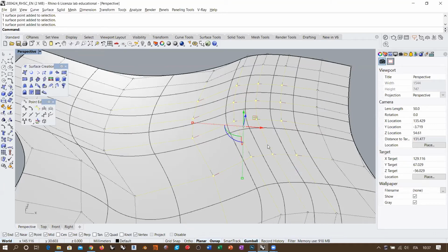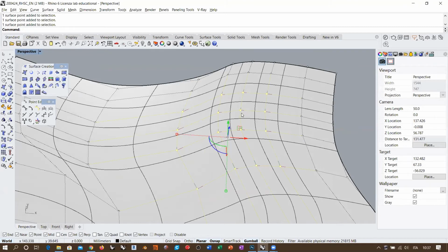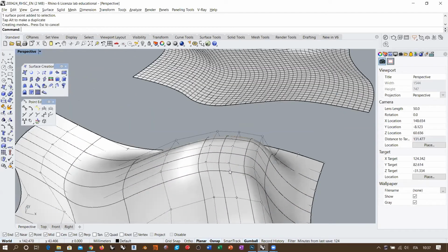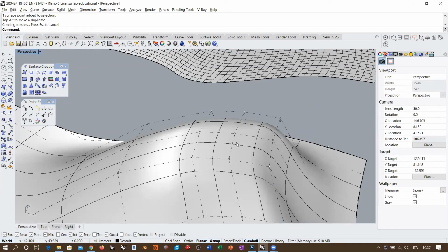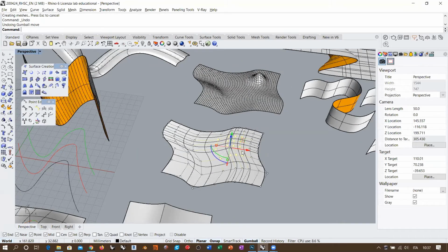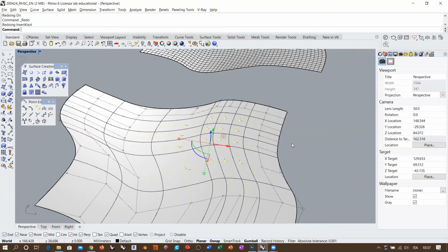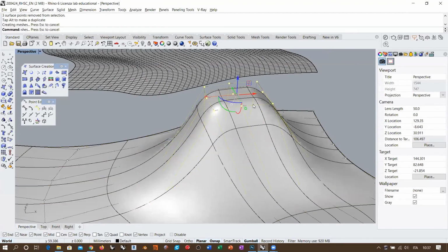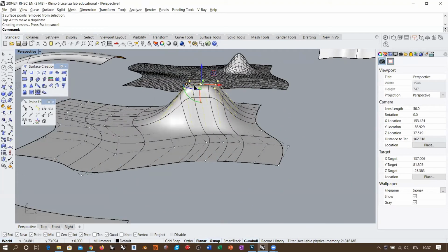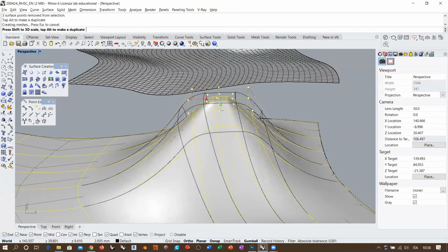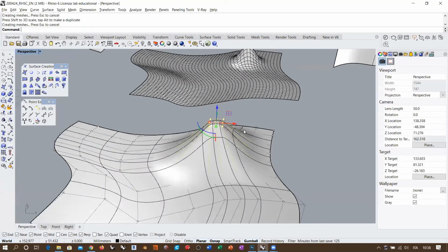So 4 by 4 control points will produce a flat area in the knot span that corresponds to the inner part of this region. So if I move everything up here, there will be a flat area more or less in this part here. Okay, so you see that we are creating this kind of nice bulge that we can control. We can control in several ways, because if I go back to this and deselect this point and this point, and I take this 3 by 3 set of points, I know that I can reach this height. If I don't want this flat-ish behavior, I can scale this set of points down, you see, and I can create this more concentrated bulge.